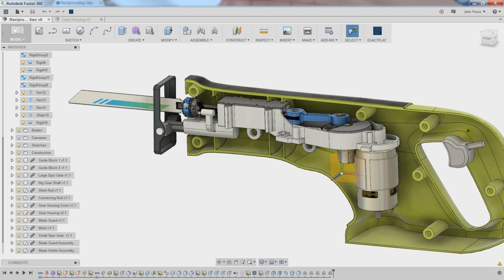Yeah, so that's actually a really great question. Unfortunately, STL files are meshes. They're not actually real CAD data. And so when you bring an STL file into a CAD system, and this includes Fusion, there's not any sort of modification or manipulation that you can do with those files. However, Autodesk makes this really awesome product called Remake. Autodesk Remake is the name of the product. You can utilize that product to convert your STL file into an OBJ file, which is a similar mesh file.